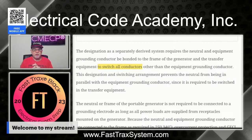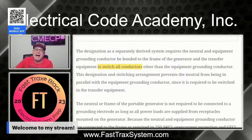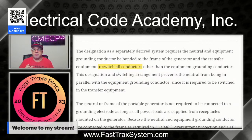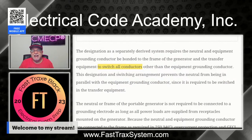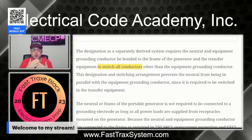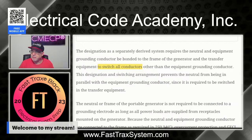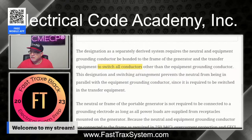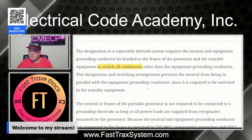That is so important. So if I use a portable generator, and I just go buy a bonded generator that's a separately derived system, and I go install it at my house, now what I've got is what? I've got a transfer switch. If I'm not going to switch all of the conductors, even the neutral, then the problem is I've got a separately derived system that I'm placing on a system, and I've got a problem here. The problem is if I don't switch the neutral through transfer equipment, now I've got parallel